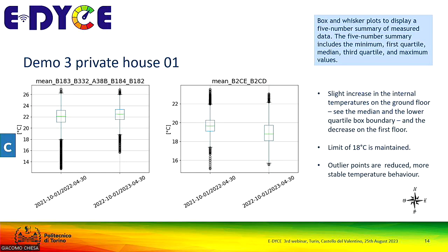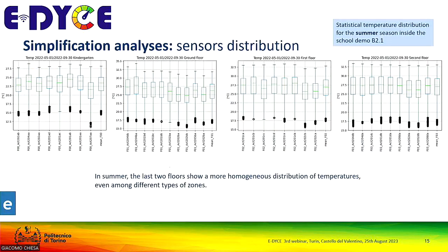But it's also evident that the comfort slightly improves, and the peak variations are reduced. When you add insulation, you may have some problem in summer of overheating, but you can manage it inside the school, inside this building, with fast ventilation.